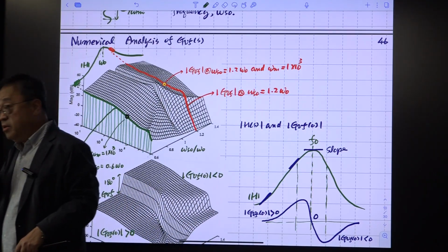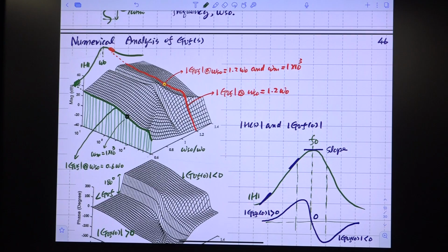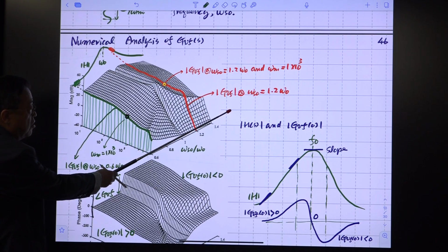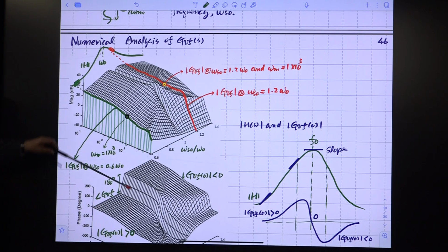Okay, so I mentioned that was just the conceptual illumination, not the exact one. Okay, this is the exact one. This plot was this one, the frequency to output transfer function of the parallel load series resonant converter. Right. So it is the ratio between the unmodulated switching frequency and the resonant frequency, and this axis represents modulation frequency.